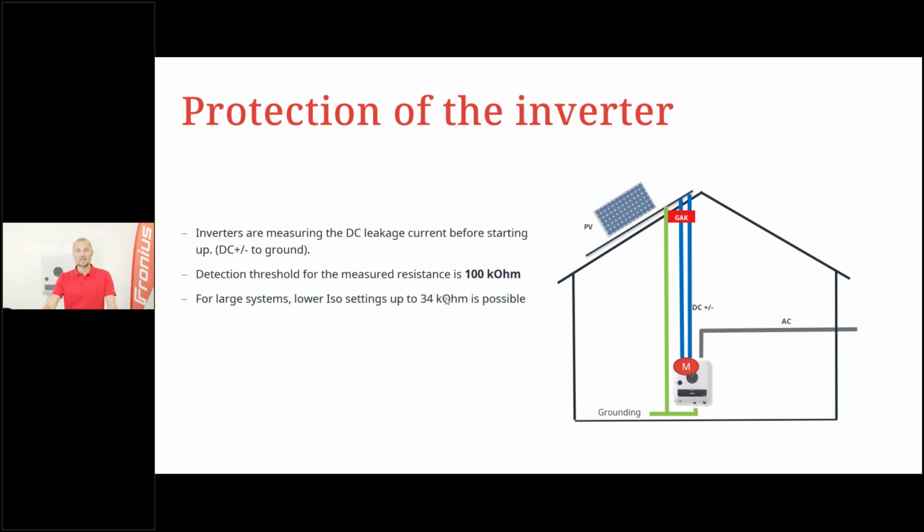This is possibly necessary for very large installations, such as rooftop installations where you have the modules flat on the roof, for example a metal roof, where you will see that 100 kilo ohm is probably not achievable, so you will have a smaller resistance.